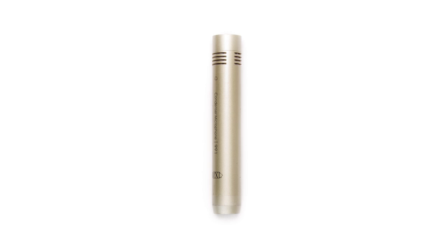Small diaphragm mics are more accurate and have less of that off-axis coloration. Because of the smaller mass, they can respond faster to changes, so they are said to capture transients better than large diaphragm mics. With all of that said, these differences are subtle, and what looks like a big difference on paper can be almost imperceivable to the ear. Also, microphone design can change the way a microphone behaves. The main thing to take away here is that there are differences in microphones, but they can be very subtle. The best way to get a feel for what works is to try out a few microphones. Let's check out an example of what a large and small diaphragm condenser sound like.